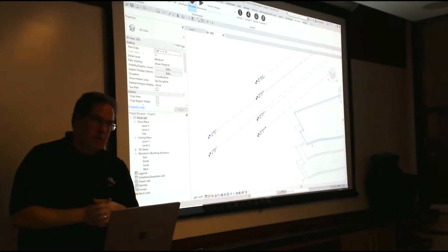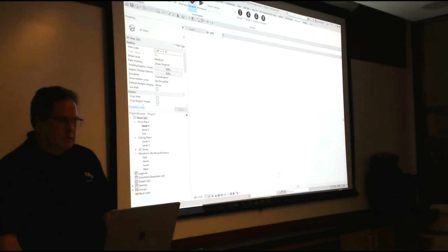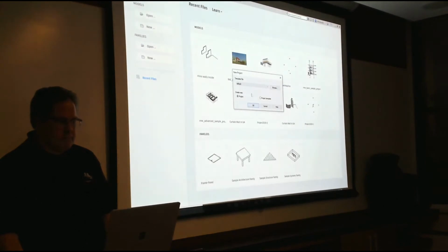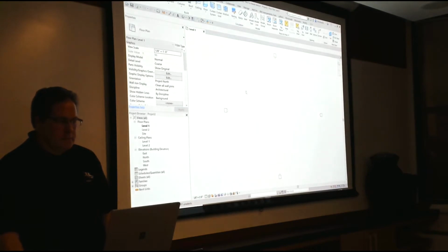Okay. Yeah. I was going to say, I think it's great that you're talking not only from Rhino to Revit, because when I'm in both, I tend to also explore a lot of Revit through Rhino, just to test out 3D clashing and to make sure that I feel comfortable that in 3D everything is great. But talk a little bit more, as you go through the examples, about how to bake the geometry and control that, because sometimes when you want to replace it, how do you replace quickly? Look, I have 100 floors. I want to replace my 100 floors with another 100 new floors. Does it recognize the element ID, or do I have to delete all the older floors and replace them with new ones?